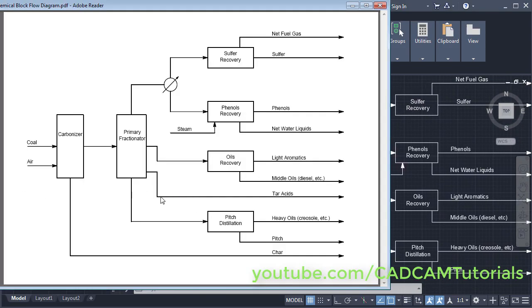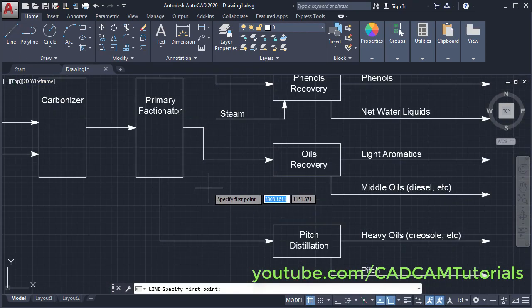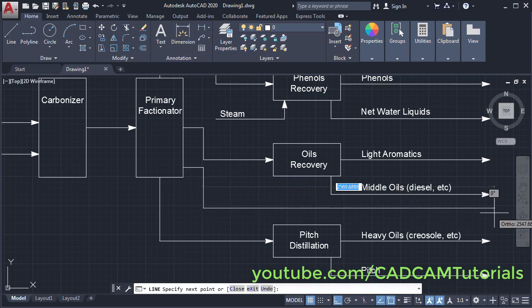Then this line. Click on line. Take your cursor to this endpoint. Drag that point. Take your cursor above and click. Then make ortho on. Then drag this endpoint, click, take it below and take it outside. Drag this endpoint and click and enter.